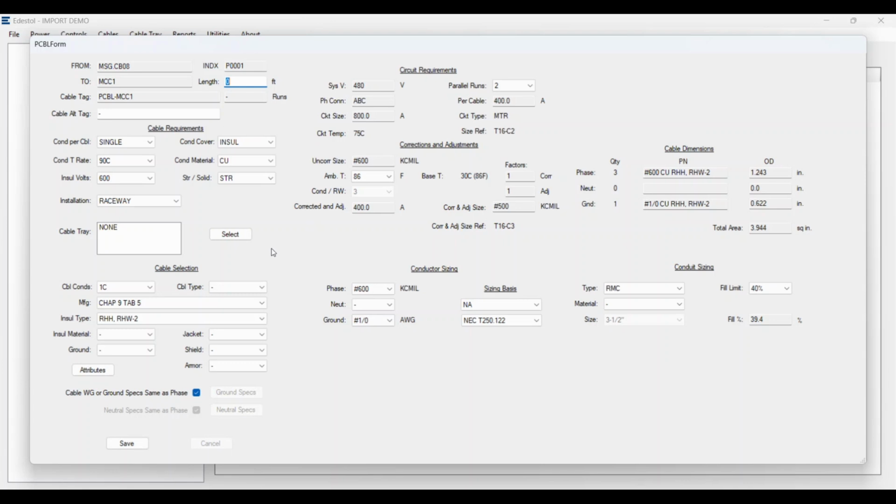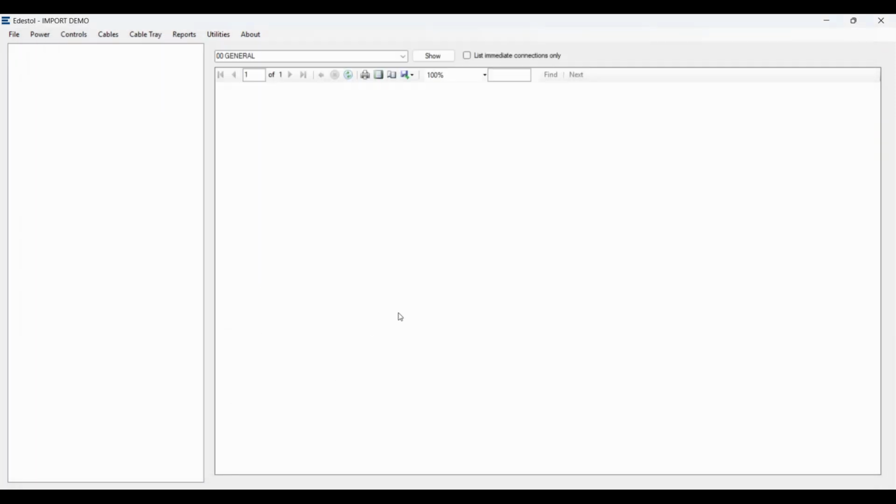And we'll have to create our cable, let's do Houston wire and cable. We're going to stay with single conductor 90C copper stranded raceway, no cable tray in this situation. And like I say, single conductor. And since it's in the electrical room, let's just do EMT. So it's sized and the ground specs are same as the phase. So you can see you've got the same style, just a different size for your cable, actual part numbers there. Looks like you need 2 3-inches.